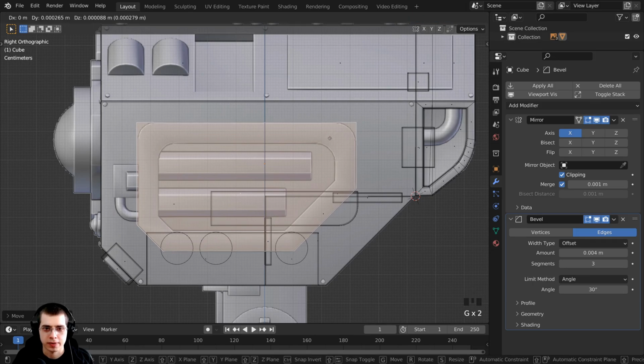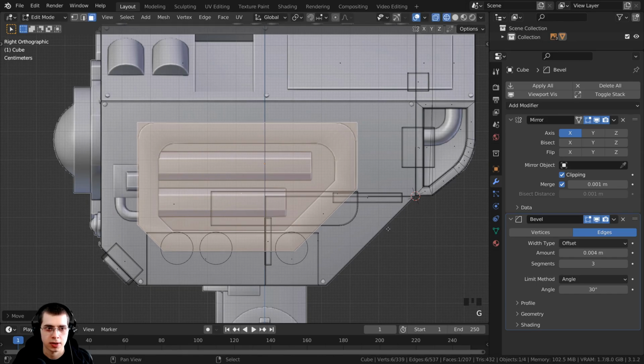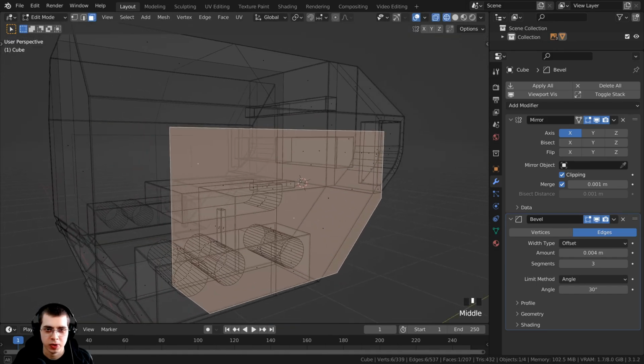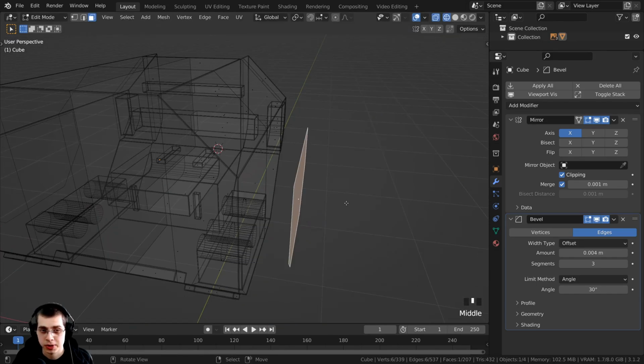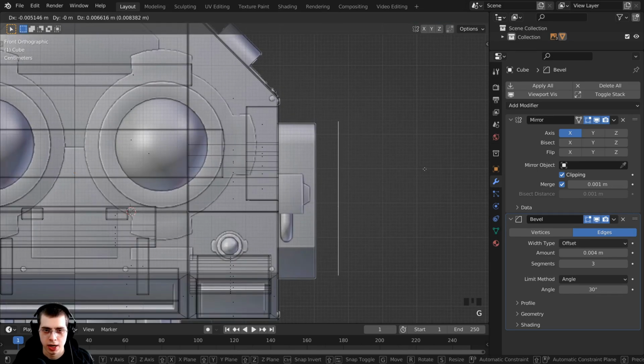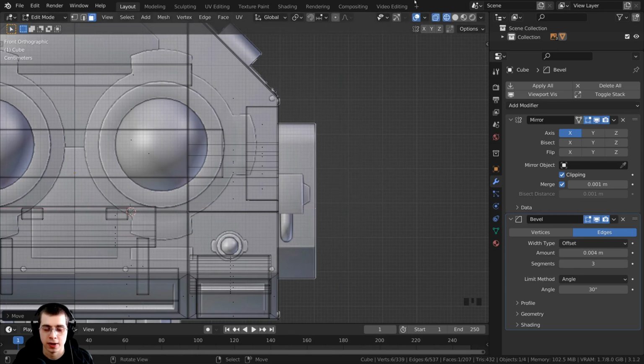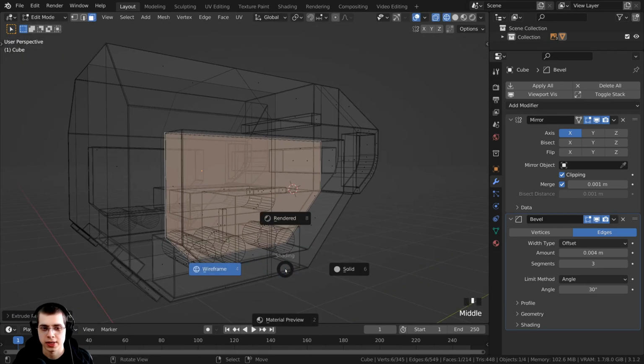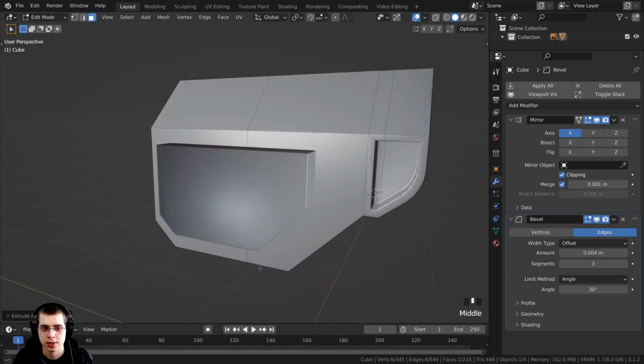And we're going to add those bevels in a moment, but mainly just kind of fit that and get the shape right. Alright, so just click and hold with your mouse wheel. I'm going to move over here. Let's also press 1 on the numpad to go to the front view. I can press G to grab, click with your mouse wheel, constrain it to the X-axis, and stick it there. So I can now press E to extrude. We're going to extrude this back into the face just like that. Alright, hold down the Z button, go back into the solid view. You can see what we've created.